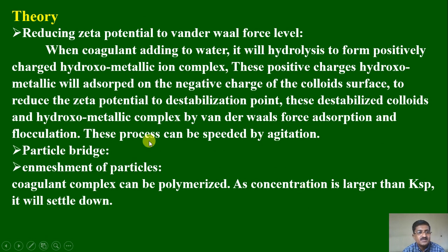Now, what is the theory of this? Reducing the zeta potential to the van der Waals force level: when a coagulant is added to the water, it will hydrolyze and form a positively charged hydroxy metallic ion complex. This positive hydroxy metallic complex is adsorbed on the negative charge of the colloid surface to reduce the zeta potential to the destabilization point. These destabilized colloids and hydroxy metallic complex undergo adsorption and flocculation by the van der Waals forces.